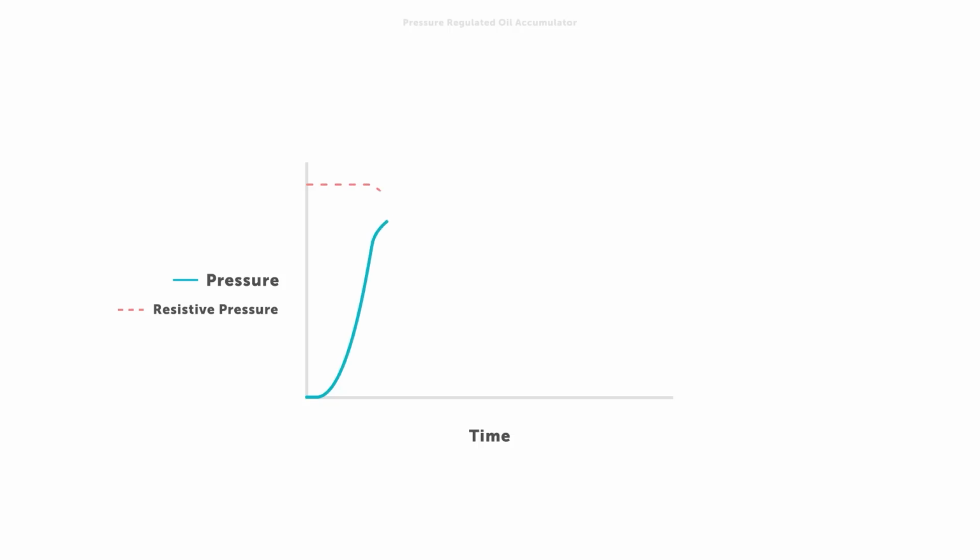In this way, we can hold the accumulator in place, causing a more rapid rise in clutch pressure up to a certain point, then bleed pressure off behind the accumulator, allowing it to move. This causes clutch pressure increase to slow as it approaches the pressure target. Depending on the specific transmission and control system, this can be coarse and clunky, or it can be relatively good.